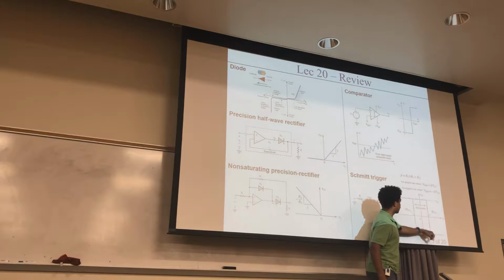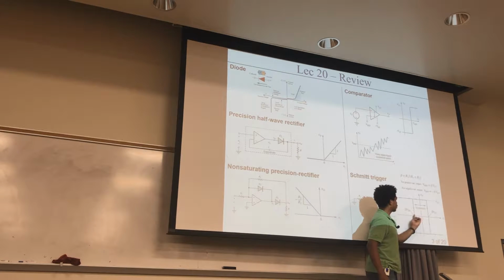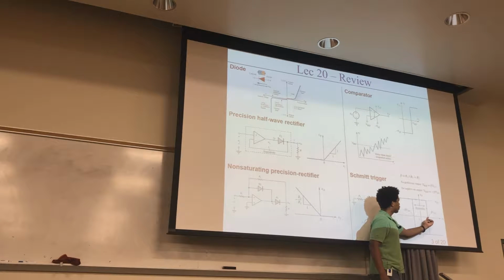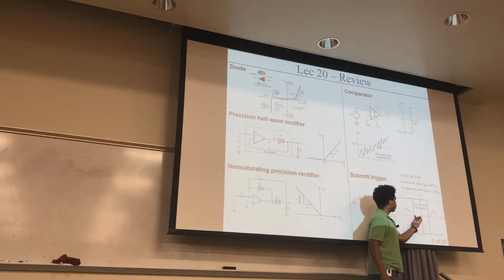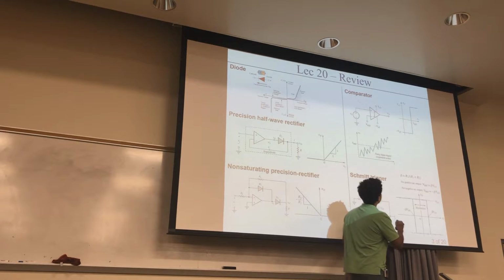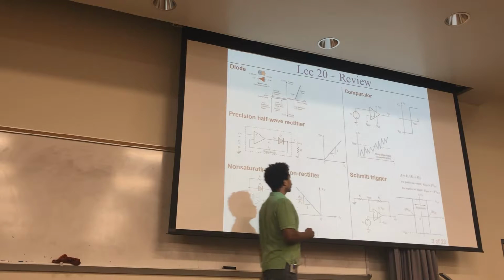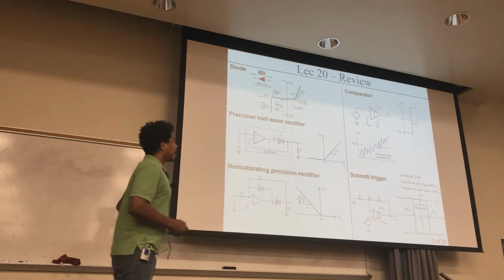So that switches as these 2 switch. And because that switches, this input has to now either climb way over here to switch or climb way back over here to switch. That avoids the noise problem you get right here, where you could just have a small little shift here to cause you to go up here or down there. Okay, so that's the Schmitt trigger.